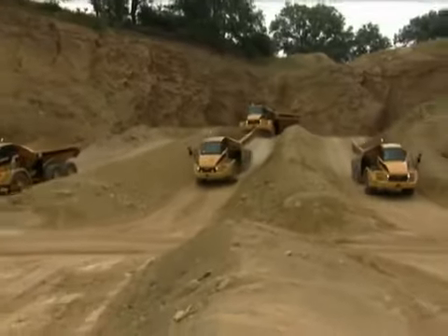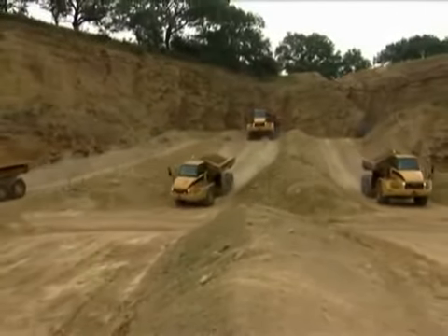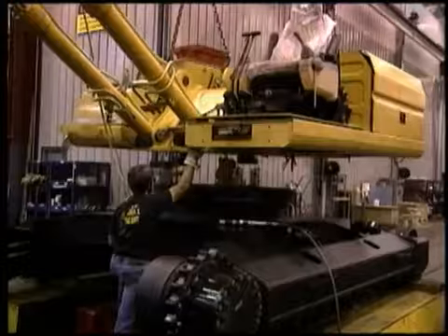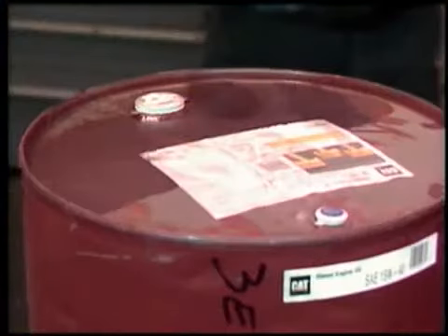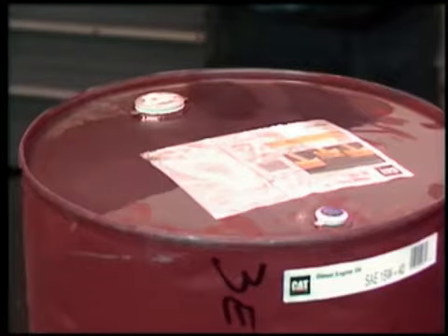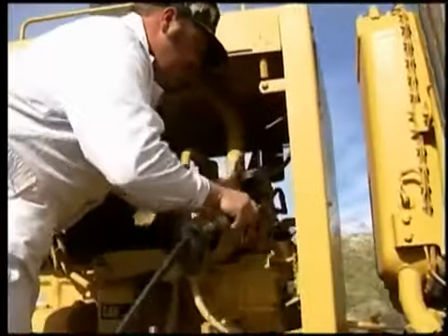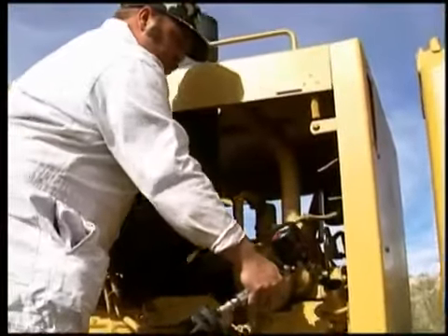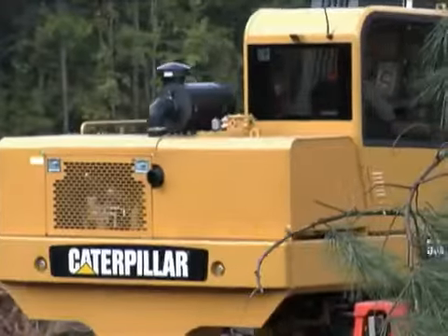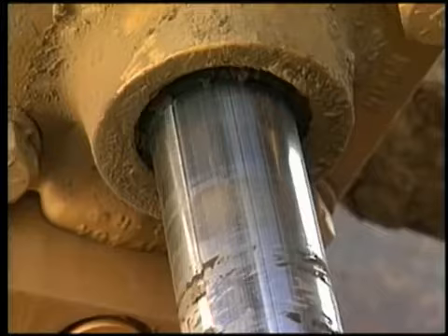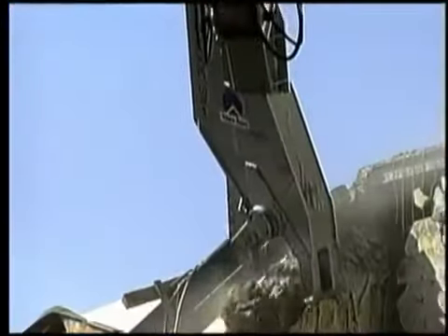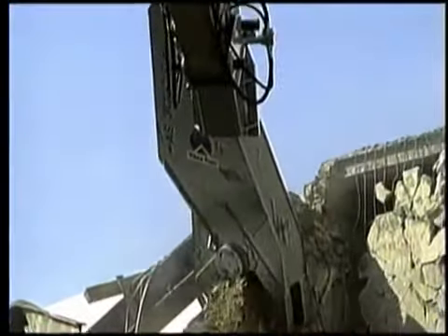Small particles can take advantage of a lot of opportunities to enter a closed fluid system. They can get in when the component or machine is built, during the storage or transportation of new oil, during maintenance and service when the system is open for repairs or oil changes, and during machine operation, such as around worn wiper seals, or when attachments with dirty connectors or dirty oil are changed.